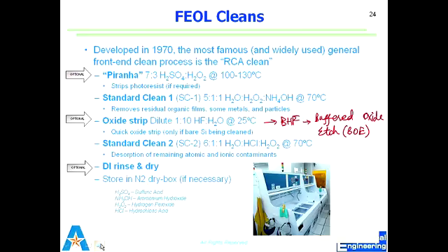Okay, now I see what you're saying. I was thinking the other way around, first hydrogen peroxide and then sulfuric acid. So here it's almost double. 3-to-6 would be 1-to-2, so it's 7-to-3. Sorry about flipping the order here. It gives a highly exothermic, very hot reaction. During that reaction, what it does to the wafer is it etches away whatever is there on the surface, right?